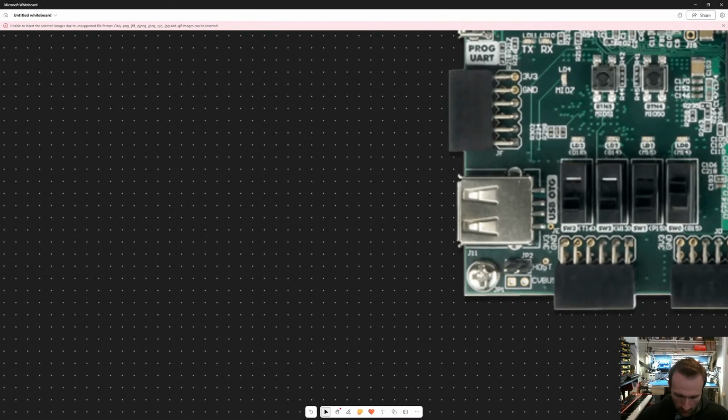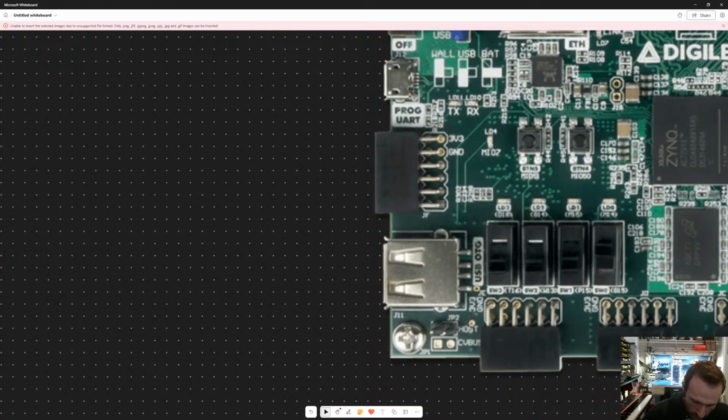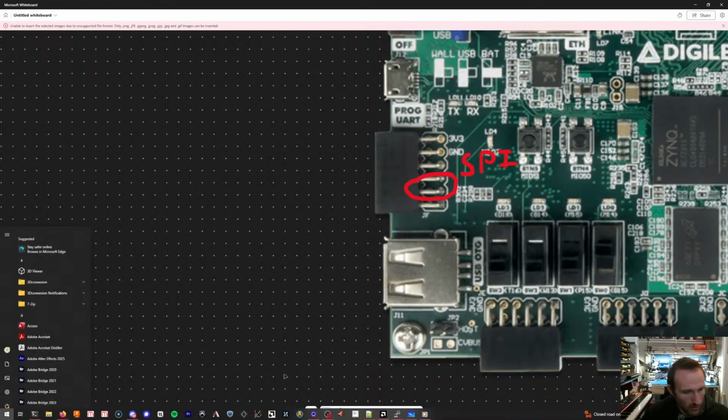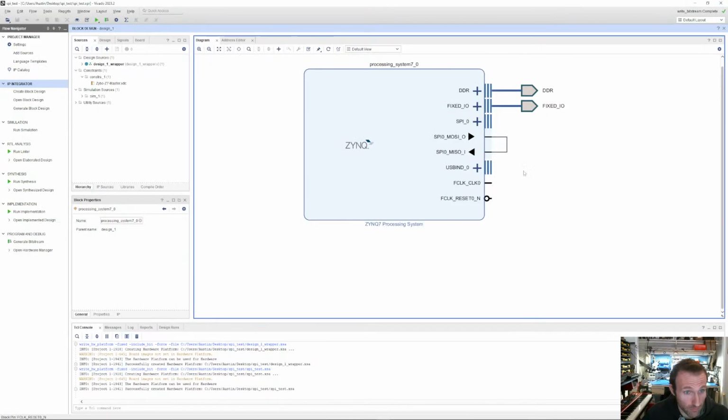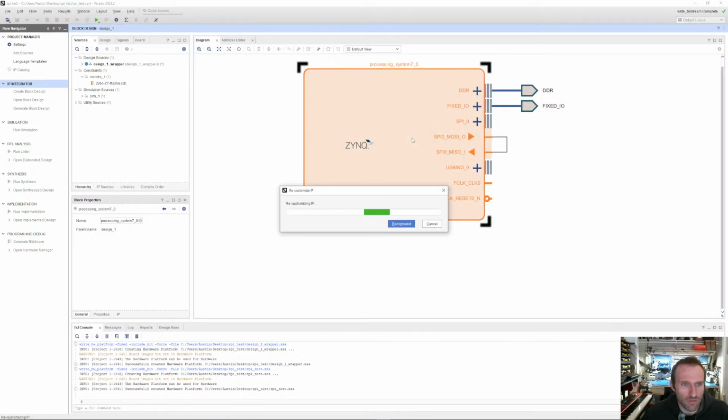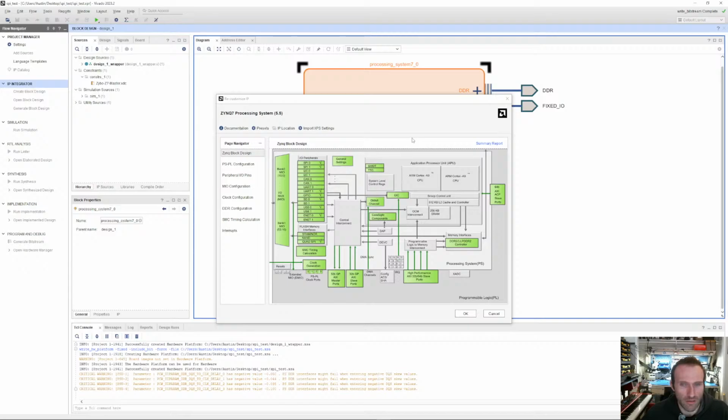As you know, these two pins are doing SPI. I think there's other pins too. Actually, let me check that real quick, so I know what pins I'm using. This was the loopback that we were just doing for SPI. If I click in here, remember there's two SPI channels. One I have as a loopback internal to the FPGA for testing purposes. The other SPI, you can see those two SPI channels here.